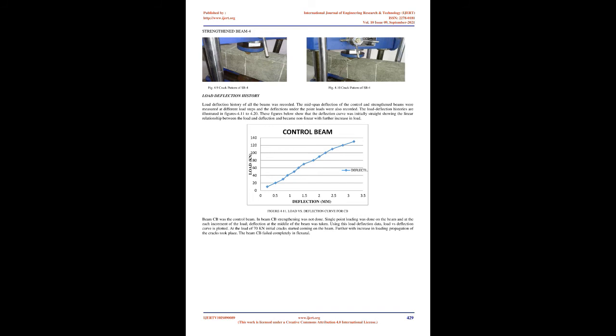Strengthening of beams with FRP sheets. All the loose particles of concrete surface at the bottom sides of the beam were chiseled out by using a chisel. Then the required region of concrete surface was made rough using a coarse sandpaper texture and cleaned with an air blower to remove all dirt and debris particles. Once the surface was prepared to the required standard, the epoxy resin was mixed in accordance with manufacturer's instructions. The mixing is carried out in a plastic container and was continued until the mixture was uniform.